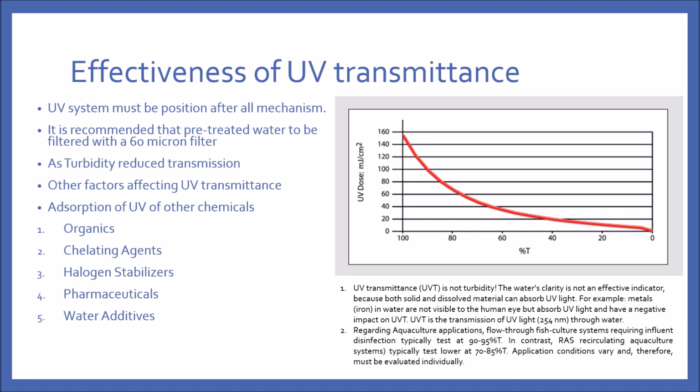One common problem we see in UV reactors is due to calcification. As you are running your RAS systems in saltwater condition, it is common for calcification to take place. Once calcification takes place on the UV lights, the UV is no longer reaching the pathogen effectively, and hence reducing the transmittance value. And in return, reducing the actual UV dose that is used to kill the bacteria, rendering your UV ineffective.